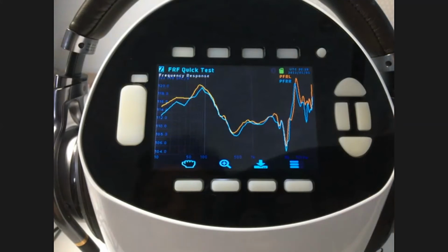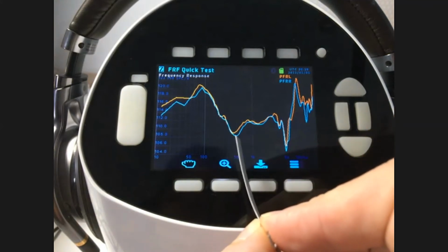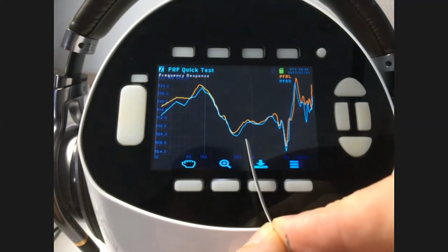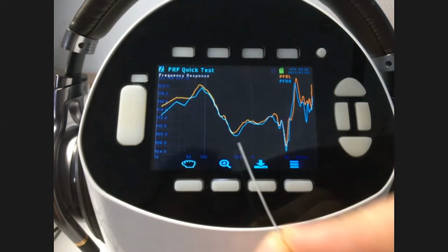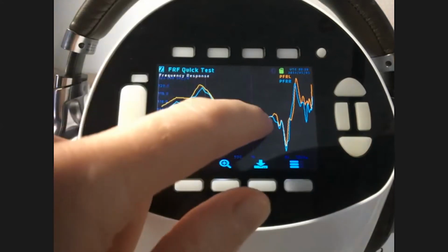Now this is an interesting thing because you have a dip right here. You'll see this in over-the-ear, closed-back headphones. That's the tuning port of the rear side. In a speaker, you have a bass reflex port, and then you have this tuning frequency of the bass reflex port. The port on the back cup of a headphone is the same thing, but it's putting that energy to the outside world and getting it from inside the ear cup. So that's why you have the opposite effect.